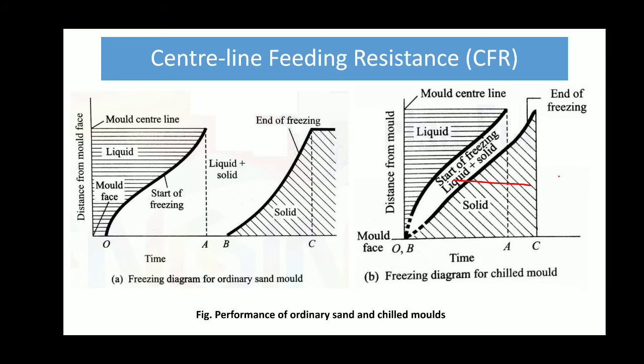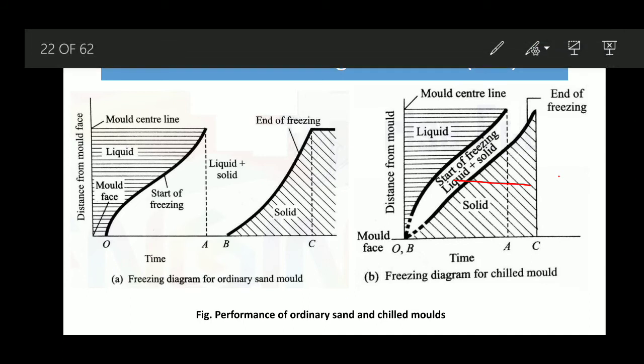Now here you can see at this mold center line, the start of freezing has occurred. By that time, when it has started freezing at the mold center line, if you consider the face, that is distance from mold, here it is almost zero, and at that position it has still not solidified.